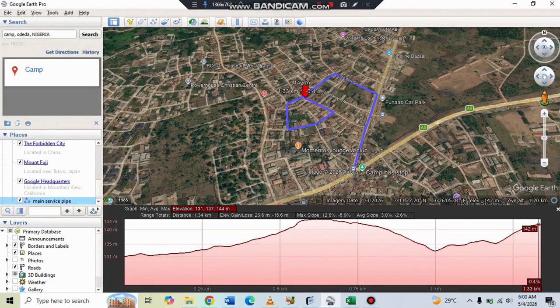So that means that when you are going to apply this in your software, the reservoir will have an elevation, and the reason for this is because the reservoir has to be located at the highest elevation point so that water can either be sourced by gravity or flow by gravity. That depends on the nature of the water supply system you are working upon.